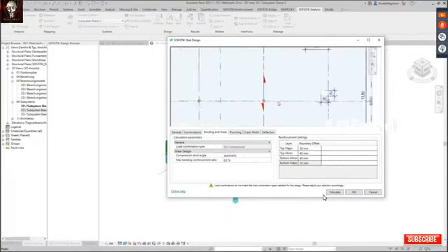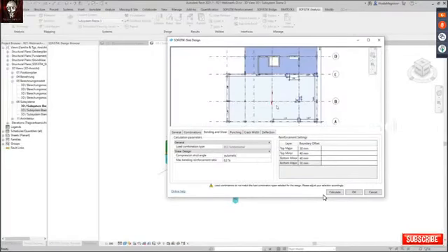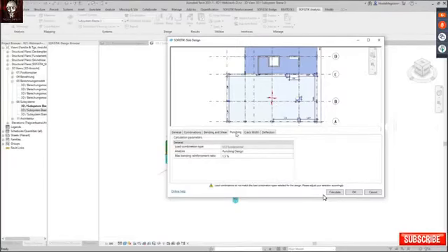This preview has been reworked, so you also have some dimension lines to orientate and see how big is your slab and how big are your, for example, spans. Now the punching, so staying in ultimate limit state design, punching check, this one is already known from previous versions. You can select between the design itself and just the checking. What has been added is, again, here's the reinforcement ratio.